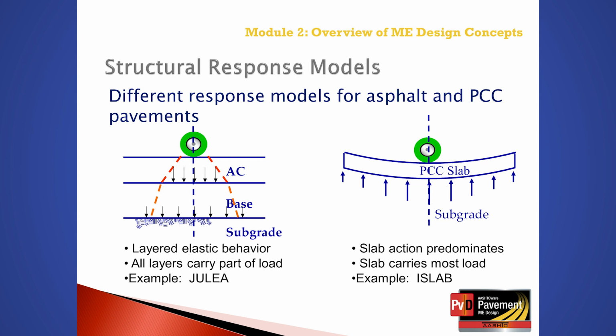The Portland cement concrete pavement structural response model is based on finite element analysis for slabs on an elastic foundation, which is illustrated on the right side of the screen. A finite element analysis-based response model is used to simulate and include the impact of free edges, longitudinal and transverse joints, and cracks in the rigid pavement. The use of finite element analysis for rigid pavements allows the consideration of curling of the slab between daytime and nighttime conditions, which is important relative to performance of rigid pavements.